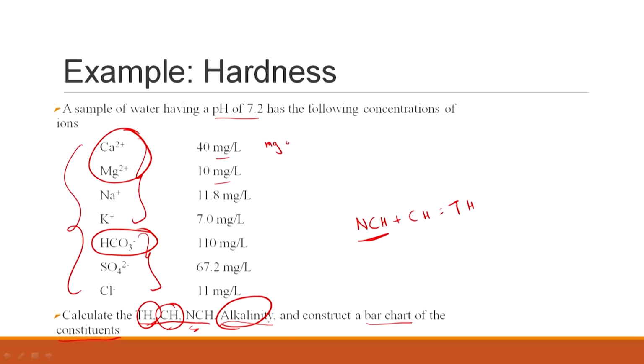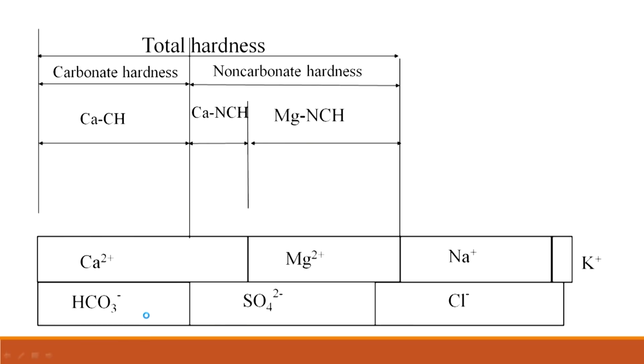Milligrams of Ca2 plus per liter of water. Here it is milligrams of Mg2 plus, 10 milligrams of Mg2 plus in 1 liter of water, right. But now we need to change the units into equivalents, right. Only then can you use it for either alkalinity or hardness and so on and so forth, right. These are relevant terms. So, what is it going to look like now?